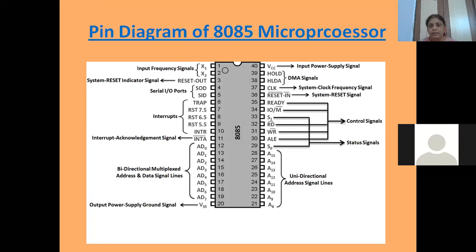तो these are 40 pins और VCC और VSS जो हैं these two pins are to give supply. VCC is to connect plus 5 volt and VSS, this pin number 20, is for grounding. तो अभी I have finished again this pin diagram of 8085. So if you have